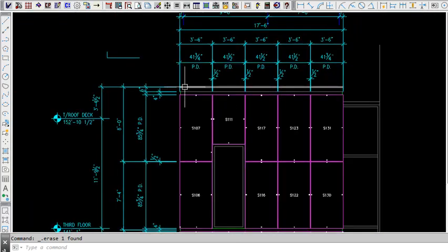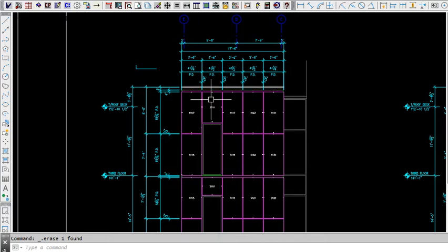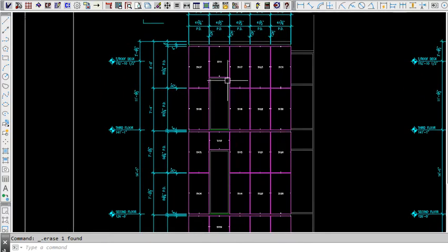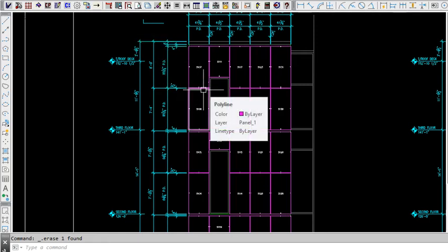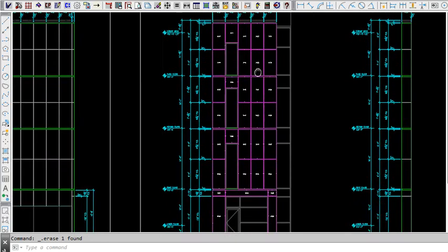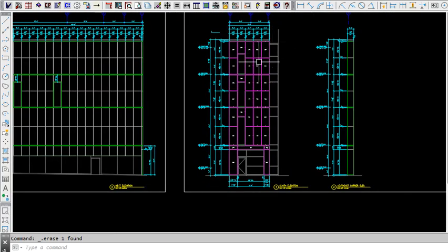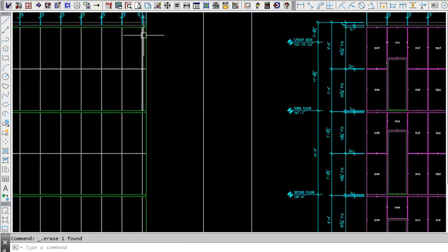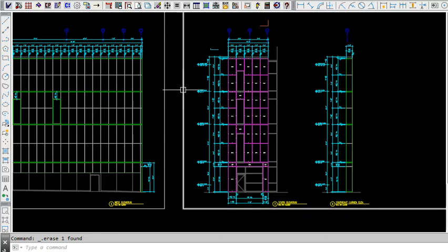So if you wanted to do an estimate on just this area of the job, you could window these and get a quick estimate. But let's link these sections and plans first, so that we get a full unfolded takeoff here instead of just the face out here, because there's really 2 faces here. There's this face and that face, and then there's this face over here with the little bitty 7 3/4 inch over there. So let's link this to the group.